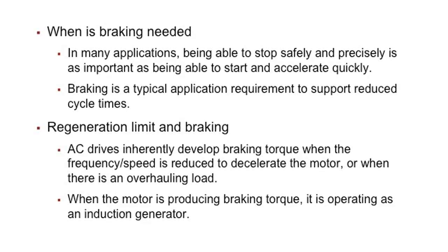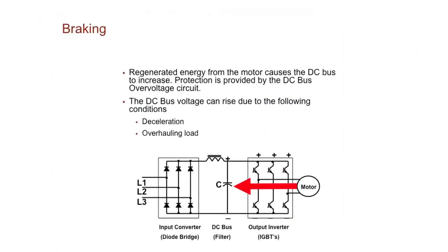When does this happen? A lot of times it's with safety, right? Maybe you've got a circular saw on a table saw and you've got a drive on it, and you need it to stop running as soon as you tell the drive to stop. Now, the thing is, if you had a motor starter on that and you just simply turn off the power, that thing's going to freewheel all day long, all right? And it's going to take minutes to come down. There's going to be a rotating hazard there.